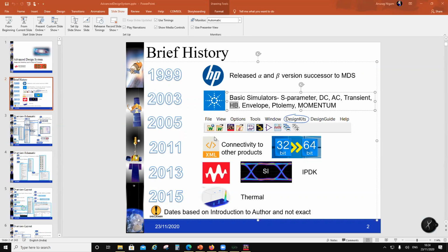They also started what is called dynamic link. What it means is you can take a circuit in ADS, netlist it, take the netlist into Cadence through dynamic link and run it. Even the optimizers would work. Basically both are running on the same machine, Cadence and ADS, and they can talk to each other. They can exchange data and netlists, so you would be able to use optimizers in ADS also. You can netlist in ADS, and I think the other way is also there.